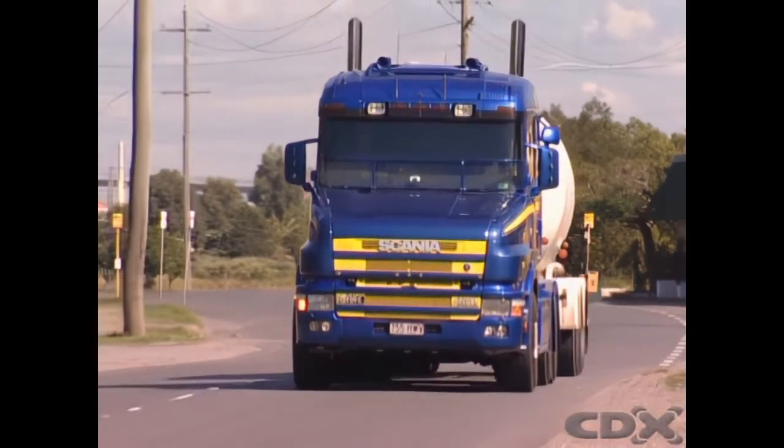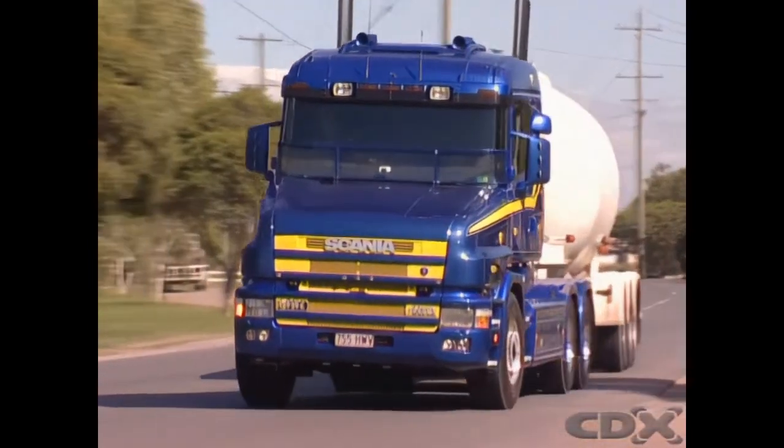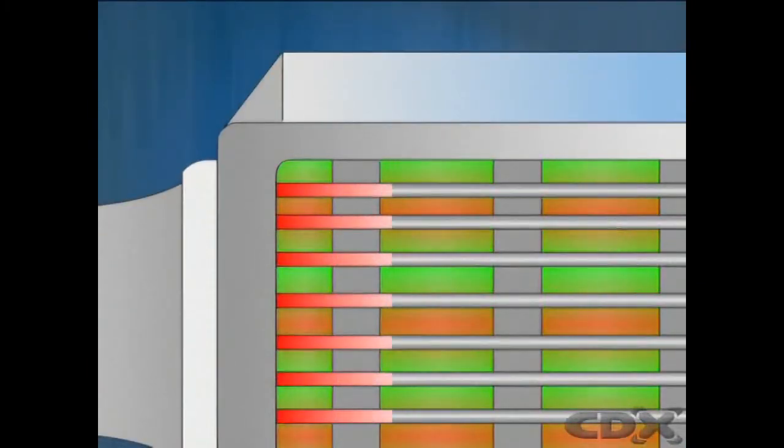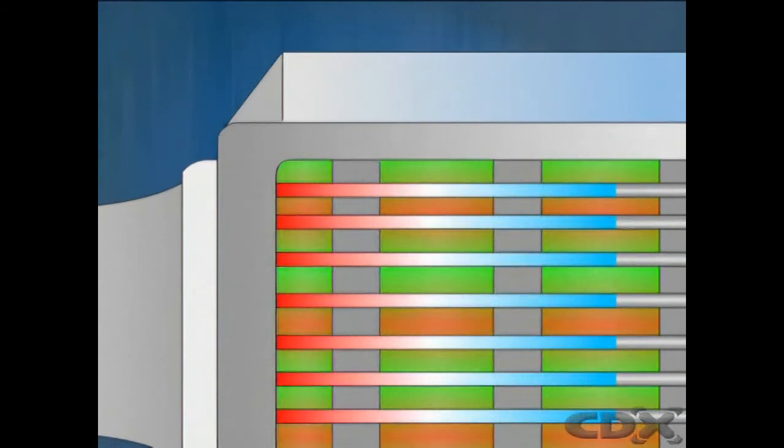Some larger engine applications have a liquid-operated intercooler. In this system, the air is fed through small tubes in a heat exchanger, and the vehicle coolant absorbs the heat and transfers it to the engine cooling system.